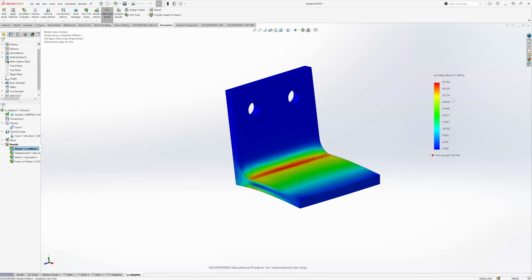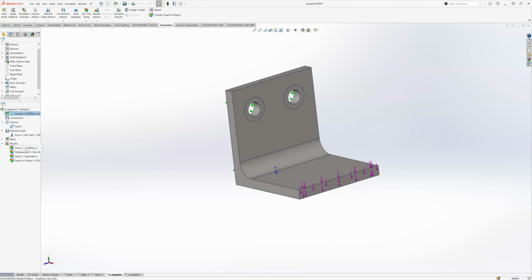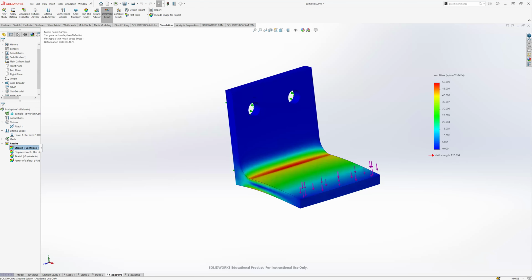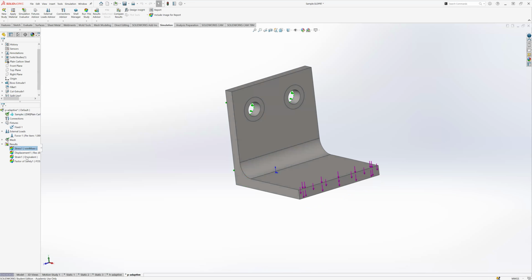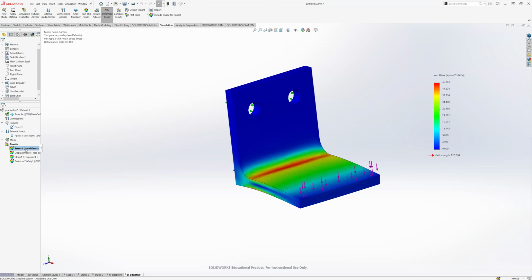Again, I'm not sure if you can see the little window that popped up, but it has a little bar and it'll tell you which loop it's on. So it's 49.14. What is our H adaptive? Just for comparison, 50 versus the P adaptive is 49. So again, they're still relatively close. They both act similarly.